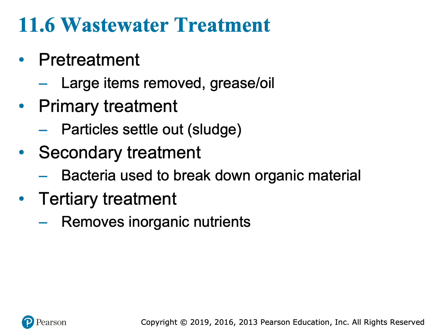This stepwise process has different treatments. In pre-treatment, wastewater first has large solids removed, such as rags and gravel, then flows into tanks where it undergoes primary treatment, and this allows particles to settle out, forming a sediment called sludge. Secondary treatment allows bacteria and other microorganisms to break down organic matter dissolved in wastewater. And advanced treatment, or tertiary treatment, which you could put for that last blank, is used to remove inorganic nutrients from the water.